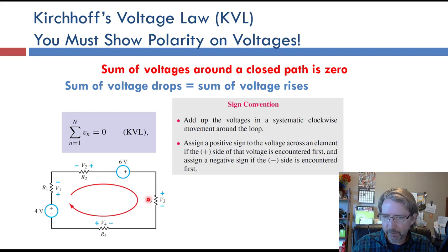Now we're coming down because we're going in a circle, so we add V3. Notice on the left, we add V1 and it's got minus on the top. On the right, we're adding V3 and it's got plus on the top. So remember, we're going in a loop, and then we're going to subtract V4 as we go along. The polarity on left and right and top and bottom is different because we're going clockwise.